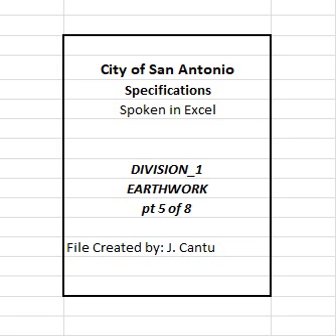Construct embankments to the grade and sections shown on the plans. Construct the embankment in layers approximately parallel to the finished grade for the full width of the individual roadway cross sections, unless otherwise shown on the plans. Ensure that each section of the embankment conforms to the detailed sections or slopes. Maintain the finished section, density, and grade until the project is accepted.